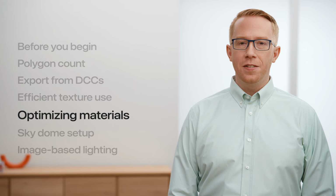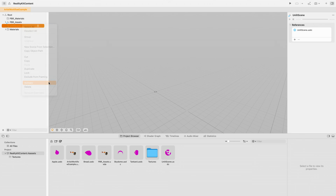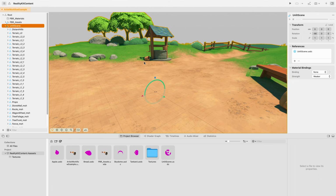Next, let's look at our scene and discuss optimized materials and shader choices. I brought in the scene we saw earlier to go with my individual assets. This entire scene uses unlit materials, with most assets only using a single texture. I've accomplished this by setting up lighting in an external application like Blender and baking all of the shading information down into a single texture per object. Using real-time lights in RealityKit has performance implications. We recommend using dynamic lights sparingly and baking whenever possible.